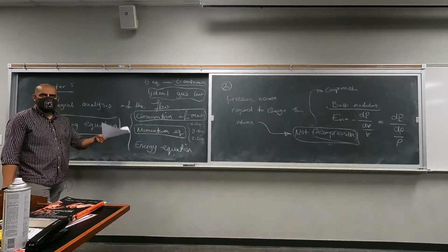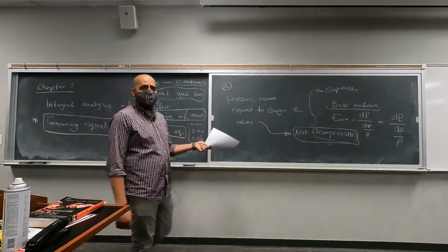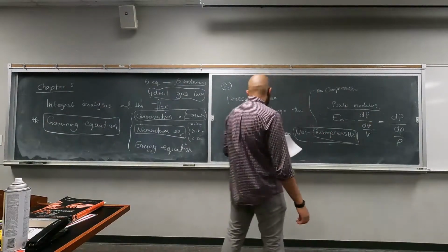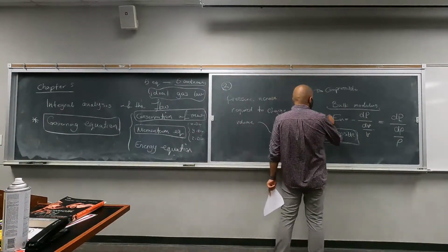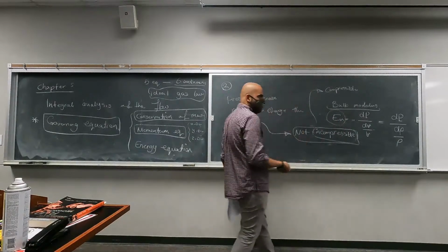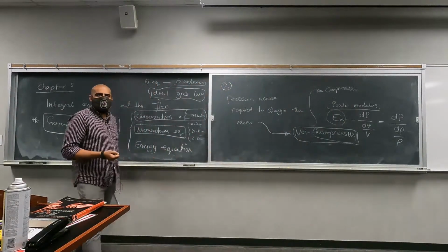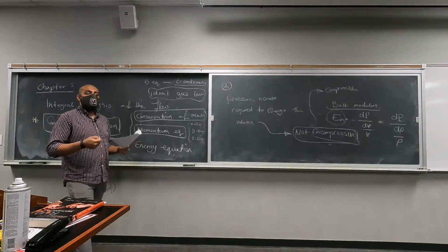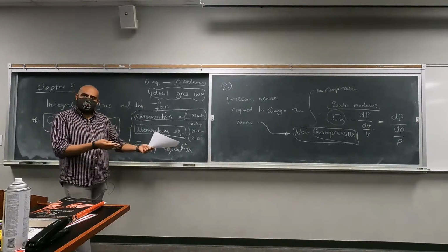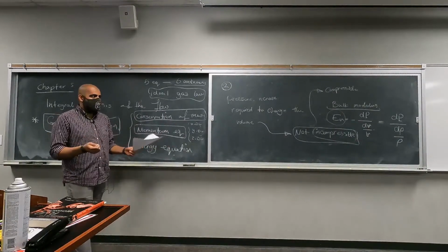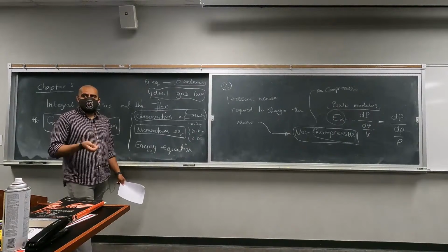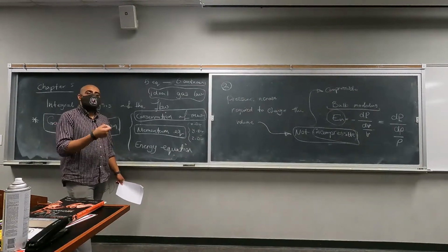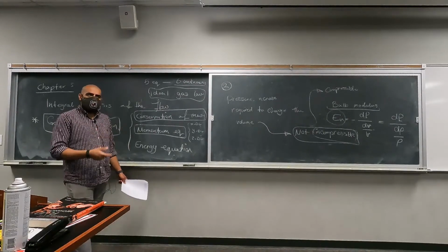This is something you had on homework. There was a problem on homework 1 that dealt with this type of analysis, the bulk modulus. Okay, bulk modulus tells you how compressible your fluid is. Since gases are usually more compressible, it is easier to compress gases. Bulk modulus is going to be smaller, so the amount of pressure you need to change the volume is lower, right? For seawater, bulk modulus is very high.